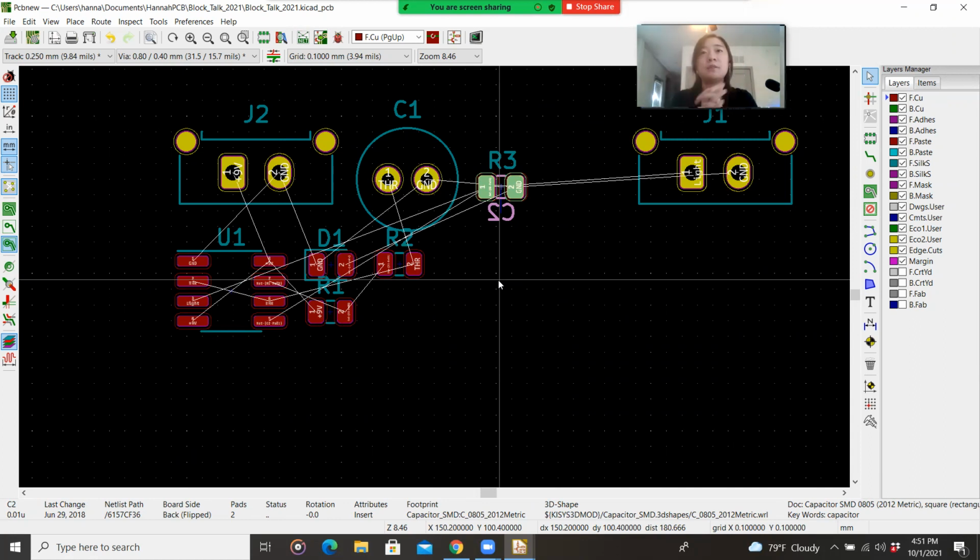They're not going to be connected to each other in any way, because the substrate layer and everything else in between are connected. So don't be afraid to move things to the backside, or to have things overlapping on the backside, if they're both surface mount components. That's okay. I know it's weird to think about, because it is a two-dimensional space that we're trying to do something three-dimensional in, but we're allowed to do that.